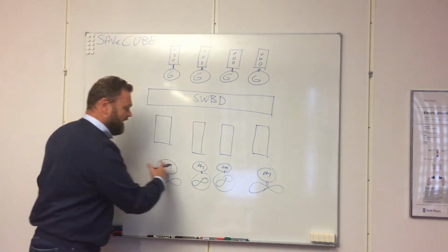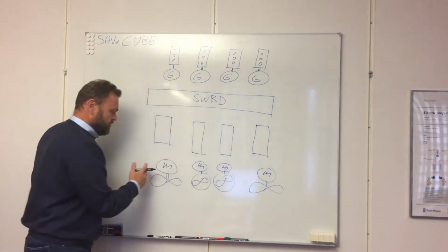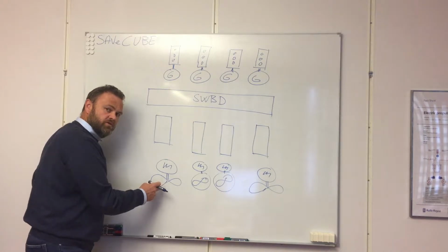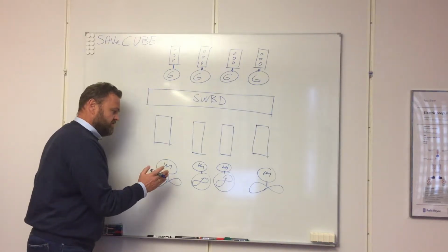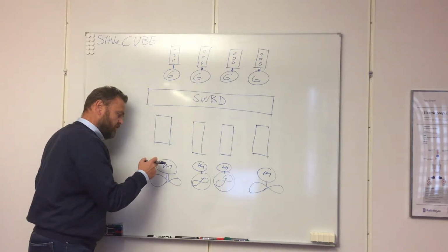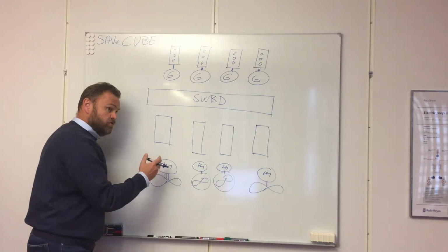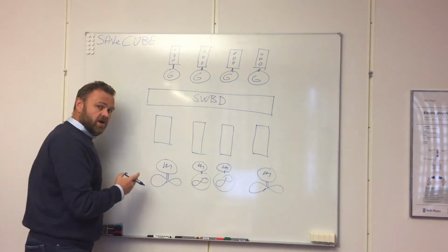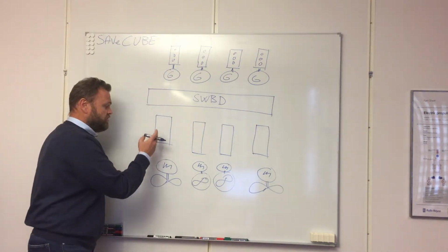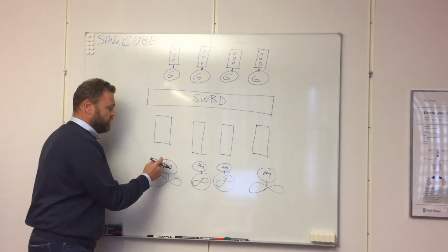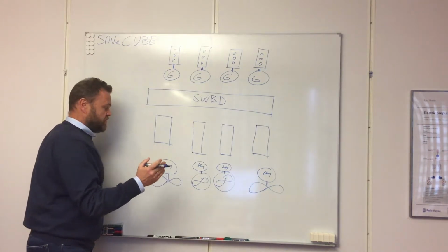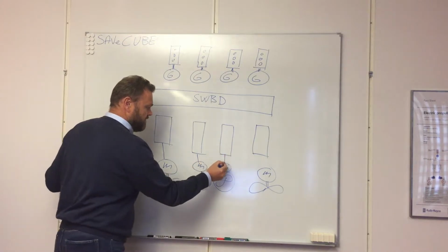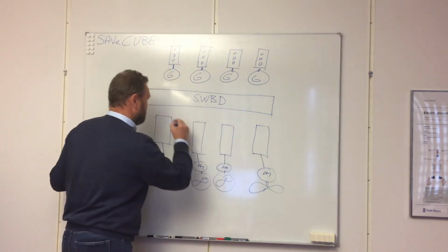And we would like to be able to regulate the RPM of the propeller. Hence, we have to regulate the RPM of the electric motor. To be able to do that, we need a frequency drive, because we need to adjust the frequency to the motor. That we have touched on in some of the other sections, so please have a look at one of them.